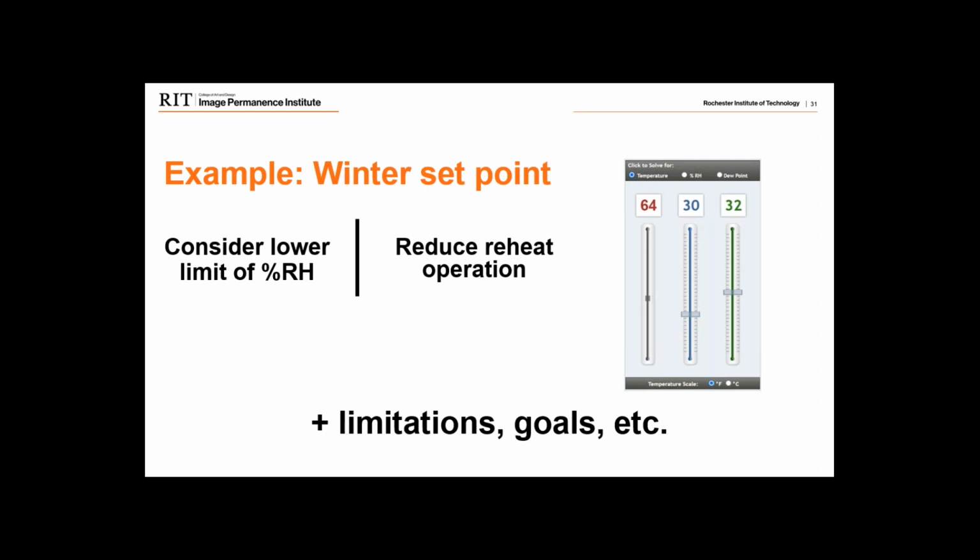And then using that 30 to 60% relative humidity range that's acceptable, I put the lower limit in there because we now are in a drier condition. Putting that lower condition on there, we can then see the coolest temperature that we can achieve, or the safest temperature that we can achieve within that range as well.